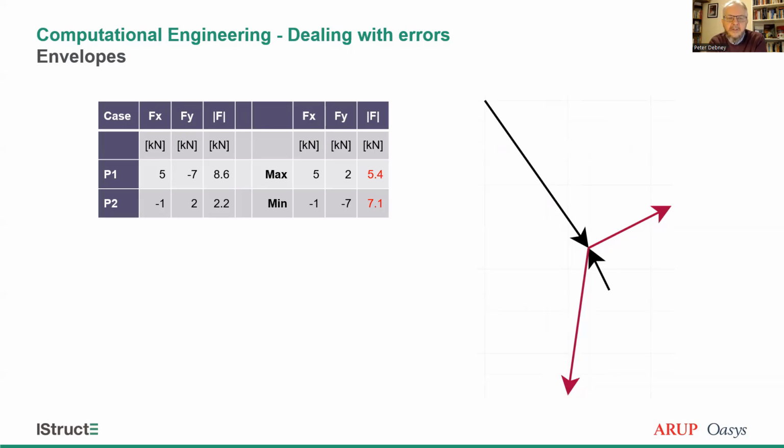But remember, if you add up forces and moments which are not acting at the same time, then you might not be designing for the actual maximums. So that is something to watch out for.